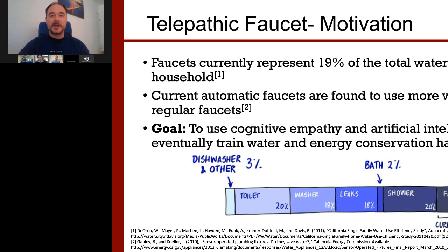But if we wanted to talk more generally instead of specifically on his Toronto application, I would say there are a few ways we could try to make the tool more appropriate for your specific application. The first one, and definitely mandatory, is that this tool currently uses weather files for California. And if you want to create a draw profile for somewhere like Toronto, California weather is going to be pretty darn inappropriate. So we need a local weather file. Fortunately, a lot of weather files are available, so that's a hurdle we should be able to overcome, but that's pretty much mandatory. Then we would also want to look at some of the assumptions used in creating the Title 24 draw profiles and how you want to respond to those assumptions.